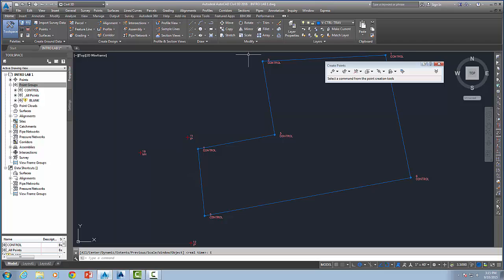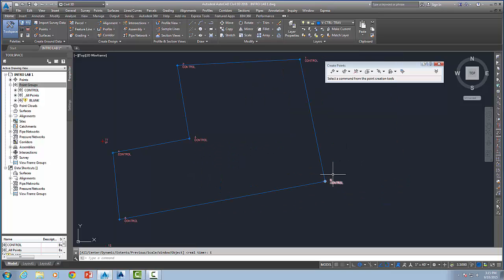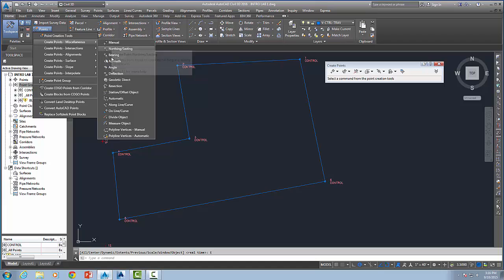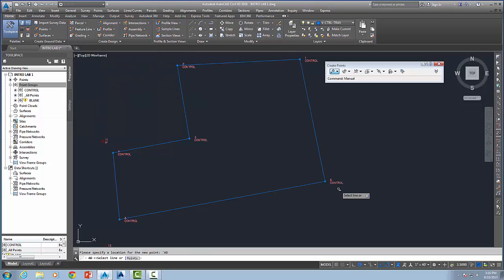So what we're going to do now is come over here to point 6, and we're going to create point 13, which is another point of control or boundary, and 17, which is another manhole point. So I'm going to go to points, create points, and I'm going to do the angle first. So that's instrument at 6, backsight 1. There's my instrument at 6, backsight 1. This is a positive angle, so it's a positive 119, 13, 11. Distance is 58.31. Okay, and at this point then we'll give it the point number.